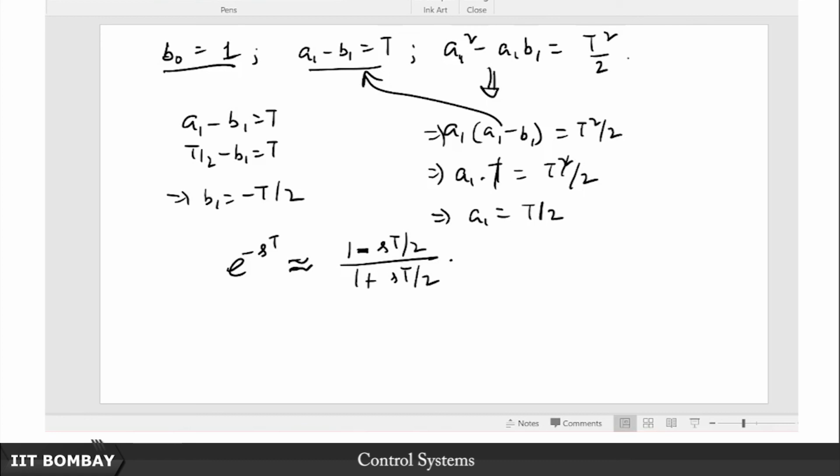So if a good controller has an additional 0 on the left half plane, then it has the effect of pulling the root locus more to the left half plane, right. It turns out that such controllers are called lead compensators, or derivative controllers, proportional and derivative controllers, PD controllers, okay. But we'll see them in somewhat more detail, and if time permits we'll also probably see a simulation example of designing a compensator for a system, but that's for a later lecture.